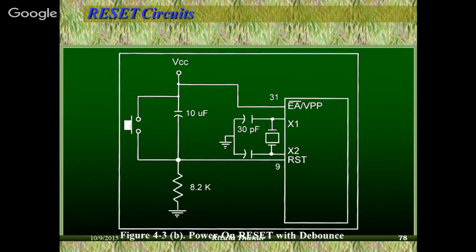One is your crystal test. What is the crystal test? See, as I told you, the microcontroller has to work on some frequency which this crystal is generating. But how do we know it is actually generating it or not? Because if it is not actually generating the right amount of frequency and the right amount of pulses, your microcontroller will not work fine. So we have to conduct this crystal test.